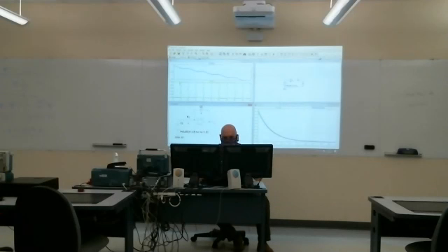It's going down because of the DC offset. It's integrating a DC, so I actually need to change this. It's probably easier to change this to a differentiator to show you how it does calculus. To get the differentiator, I need to just swap the resistor and the capacitor.